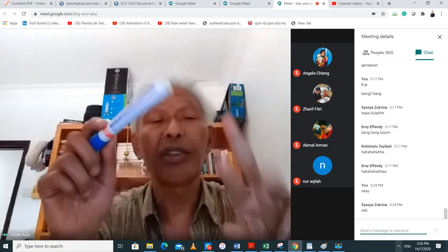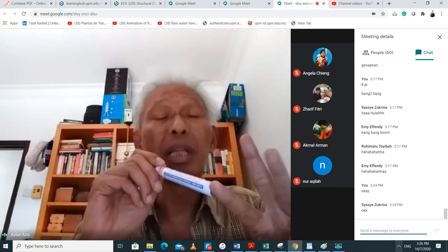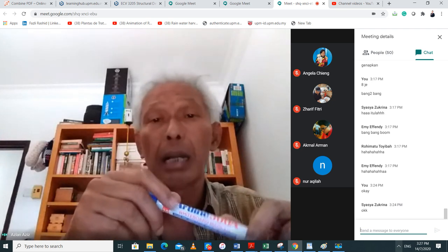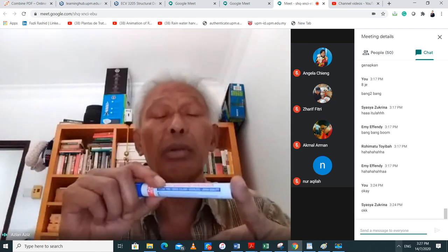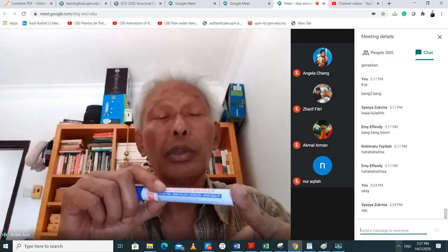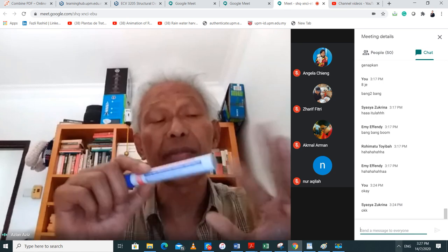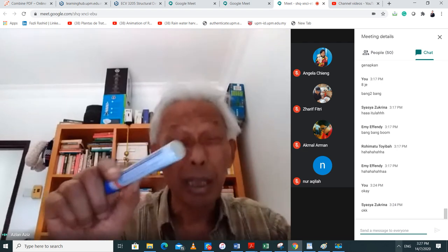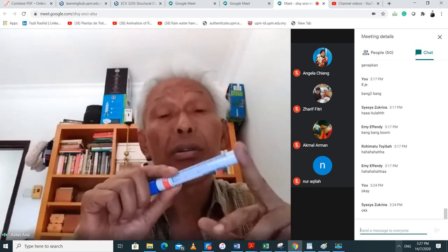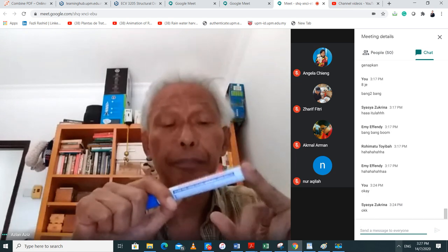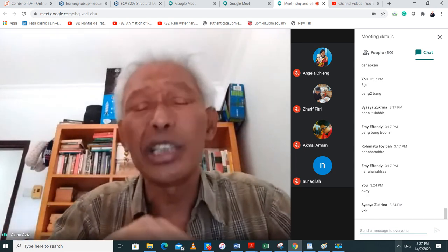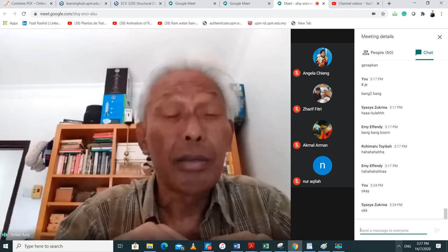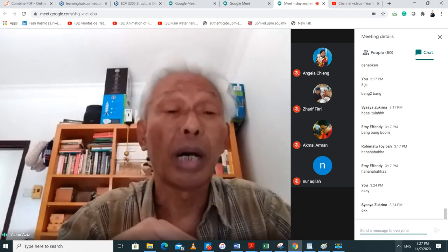And we said to ourselves, because pile load tests are expensive, maybe you can use only 3% of the piles to obtain your ultimate value. So you need only to use the static formula because this is expensive, right? The pile driving formula, you also use it to confirm your static formula prediction, all right? Then generally speaking, piles do not have problems in terms of settlement. Occasionally they have a settlement problem. So that's why you need to know how to measure the settlement.